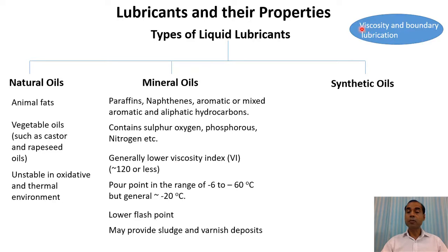And as I said before, viscosity is one of the two most important properties of an oil. In fact, if we name the one most important property of a lubricating oil, that is viscosity. So if temperature changes, the viscosity will change drastically for mineral oils.